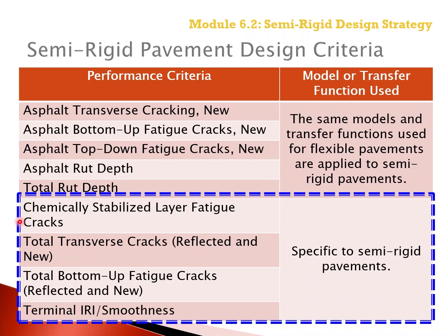We will discuss the fatigue failure or fatigue cracks of chemically stabilized layers. We will discuss the total transverse cracks, new and reflective. We will discuss total bottom-up fatigue cracks, new and reflective, as well as the terminal IRI, all of these being specific to semi-rigid pavements. So the remainder of the models and transfer functions that are specific to semi-rigid pavements are discussed within this session.